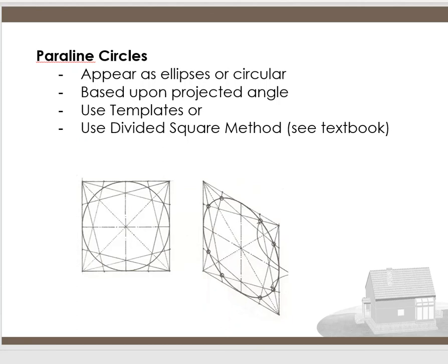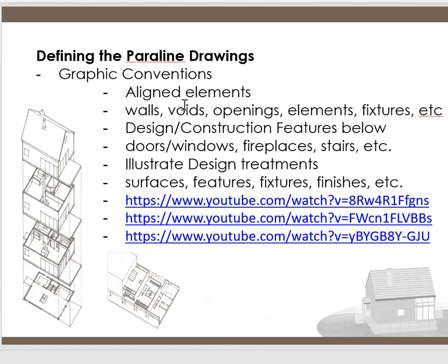So just to close out, as I said, we have this whole series of multi-view drawings, and they all line up and they just stack on top of each other, creating a beautiful three-dimensional Paraline drawing. So if you use a plan oblique, here's your plan. You start to bring up those walls, maybe the first floor, second floor, and then you start to create the roof, and see how it's broken down here. So you can use plan obliques and isometrics to really analyze an interior space.